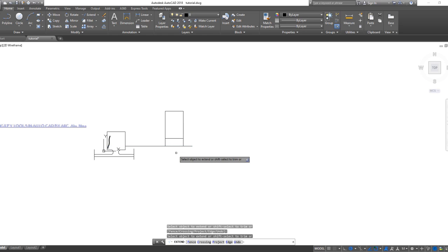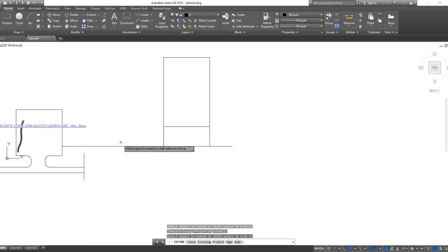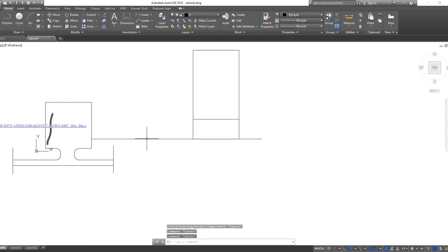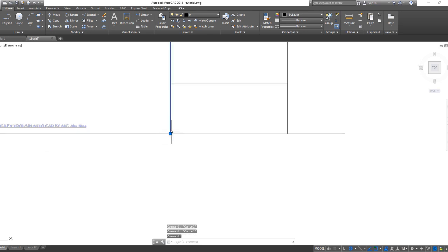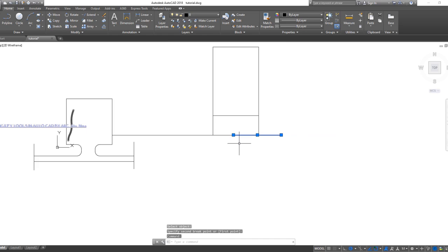So also, one of the tools I will quickly use is the breaking tool. For instance, you want to break in the middle, you want to separate the line here. You just say BR, you enter. So once you click on it, it breaks it. BR, enter. So you break, you see. So already I've broken this line now.